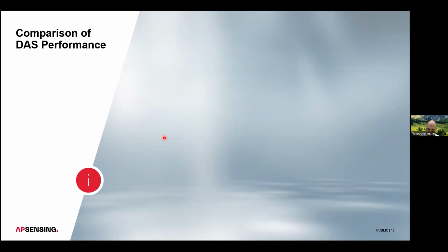Then you don't need to be concerned at all, because these scattering centers I am referring to are introduced into the glass fiber during the manufacturing process, and you cannot get rid of them. They are always there. Nowadays, the quality of glass fibers is so good that we have reached almost the theoretical limit of attenuation. As long as you use standard single mode fibers, they are good enough.